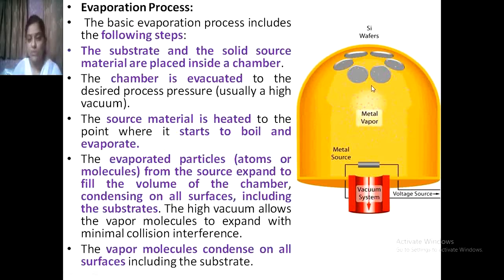Then the source material is heated to the point where it starts to boil and evaporate. The evaporated particles, that is atoms or molecules from the source, expand to fill the volume of the chamber, condensing on all surfaces, including the substrate.